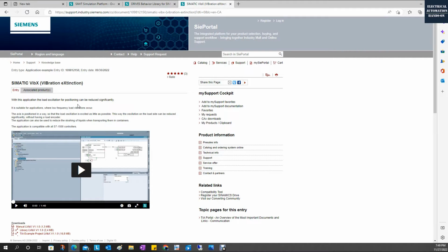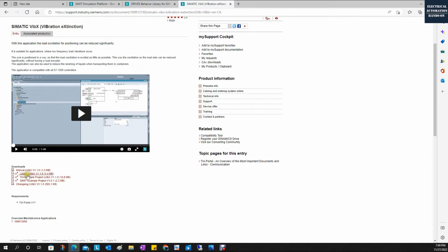Where's my load, right? This application provides a simple TIA Portal project and a SIMIT example project. In the TIA Portal project, it basically sets up two kinds of positioning control, servo drive and TO, technology object system. And the drive is using Dynamics S120, the servo drive system.